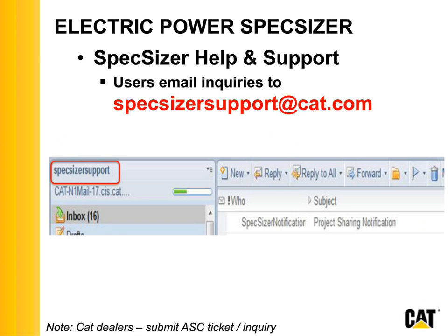And then it's really incumbent upon you, I think, to understand what you can work with to reduce your genset sizing. Do you have a lot of inrush? If your inrush is high compared to your running, then you have a lot of motors. And if your inrush is really high compared to your running demand, you need to look for a way to reduce the inrush. And so how would you do that? You'd work with reduced voltage starters, you'd work with low inertia motors.